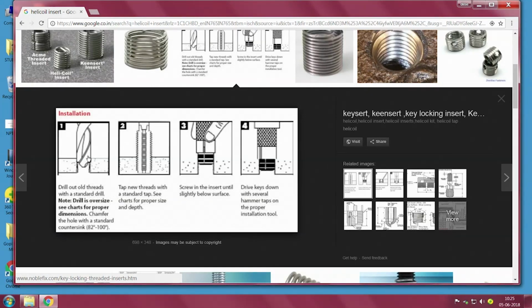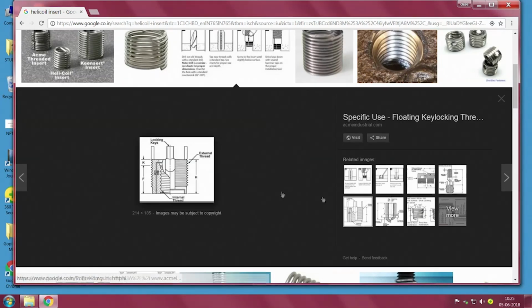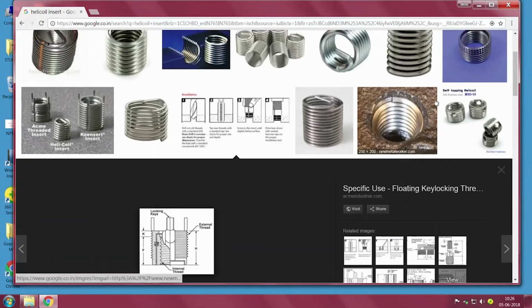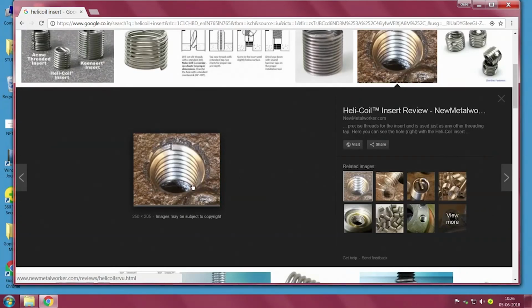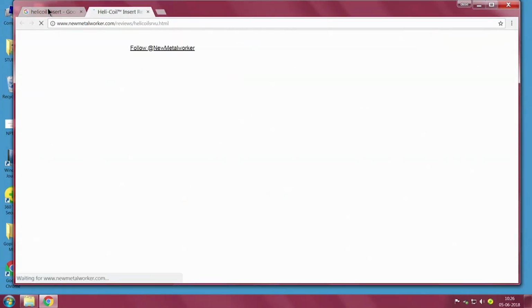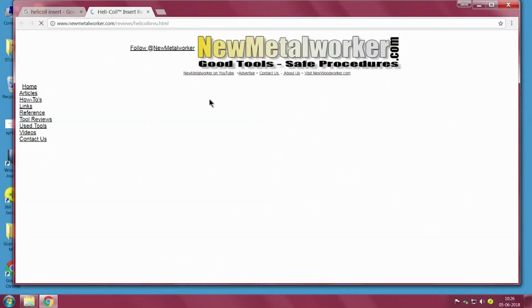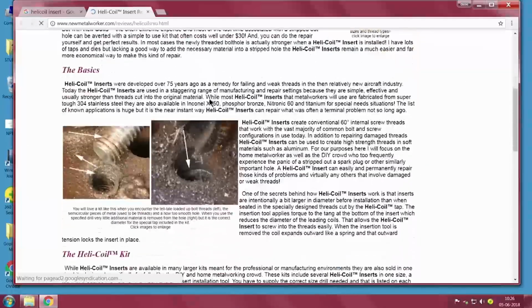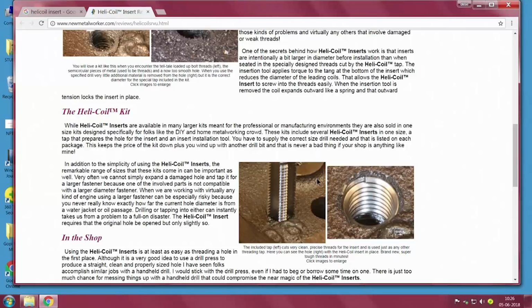This is typically the way this helicoil stuff works. You have a hole, then a special tool, then a device which inserts it for proper installation and so on. So, this is standard practice when it comes to making these things. There is a good view about it here. Of course, it is often used as a repair, but the reality is more than repair, it makes sense when we actually insert it like this. You see this?